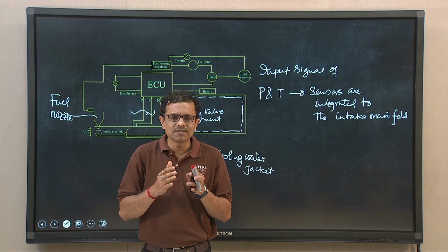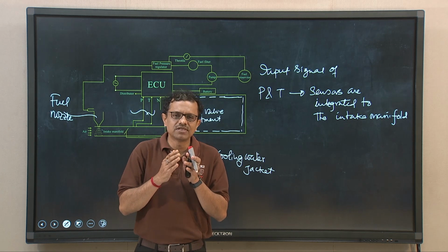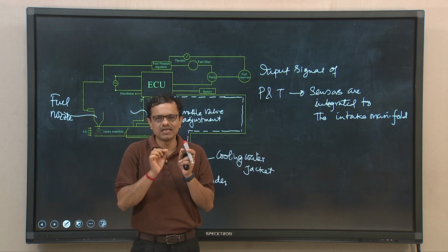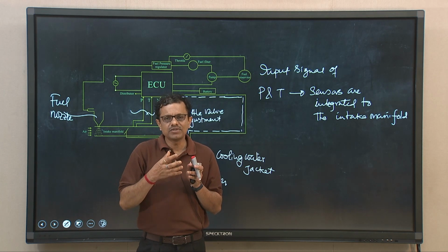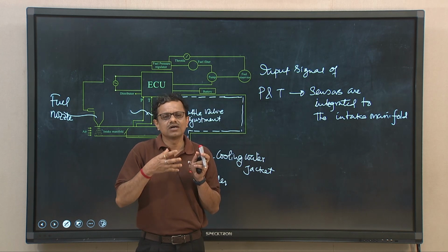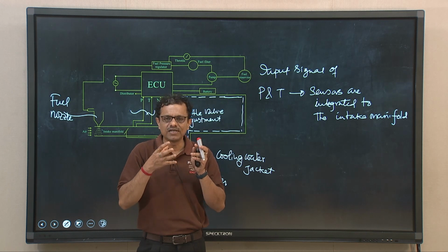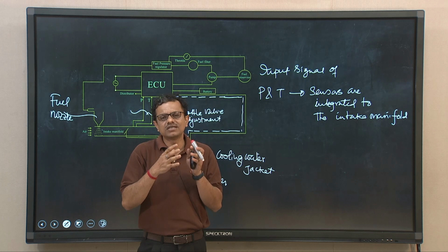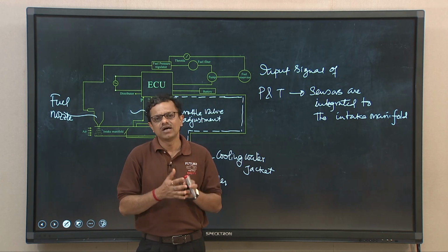The cooling temperature sensor attached to the cooling water jacket has some range for optimal operation of the engine. Now, if the temperature recorded by that sensor is beyond that value, then certainly the ECU will take preventive measures to control the combustion rate, which in turn will ensure that the temperature of the cylinder wall and the piston face remains under control.